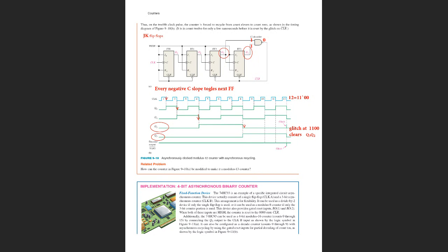So when you see the timing diagram, at the first clock and its negative slope, Q0 is toggling from 0 to 1. At the second clock, the same, flip-flop 0 is toggling from 1 to 0, and so on and so on. At every clock, Q0 is changing its state. And when the flip-flop is changing its state, it's affecting the clock of the next flip-flop.